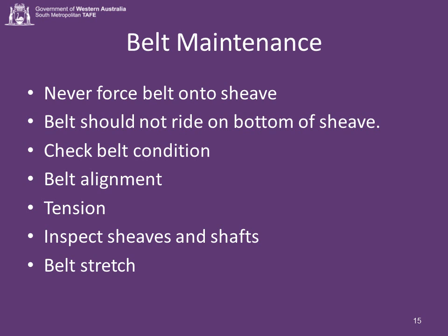Never force a V-belt onto a sheave. There have been a number of injuries to fingers and hands as a result of this. It can also break the inner strings of the belt, leading to premature failure.